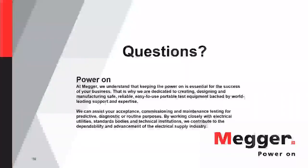No, generally, what you do is you make sure, like for our equipment, like our analyzers, we generally recommend calibrating once a year. But I've seen people not calibrate them for years because everything's working fine on it. The transducers themselves, usually, especially if it's a digital, it's so many pulses per degree or pulses per millimeter. So once you know that value, you don't really need to calibrate them again.